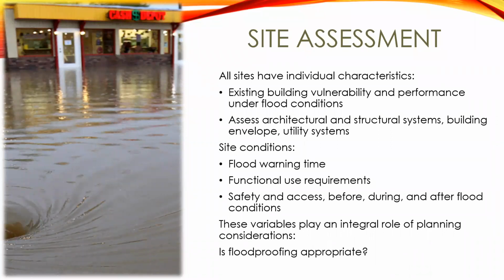We have to look at the flood warning time, the functional use requirements, and how long the building can be shut down, because it's usually a business that's running. We also look at safety and access before, during, and after the flood conditions, because if there are active measures, personnel have to get out there, deploy the measures, and then evacuate during the flood warning times.